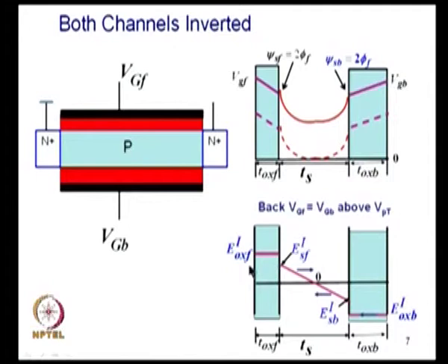You can see now, we are seeing it like this, but in the device you are able to reduce the doping here and also reduce the thickness here, the field here will be reduced. If the field there is reduced, the electric field there also is reduced. That means the voltage drop across oxide will be reduced. That means your threshold voltage will be lower in this case.